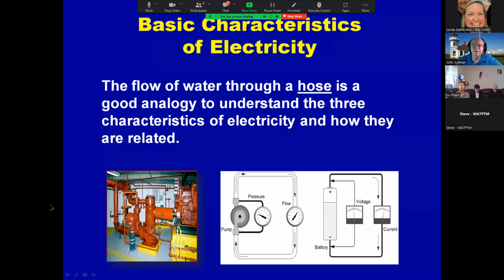And you can see in this drawing that we're measuring the pressure again across a load, in this case the pump, whereas we measure the flow in series. Here the meter is in parallel with the system, whereas here for measuring flow, it's in series. Similarly, over here, we measure voltage in parallel across something in the circuit, whereas current, we measure in line or in series. Okay.